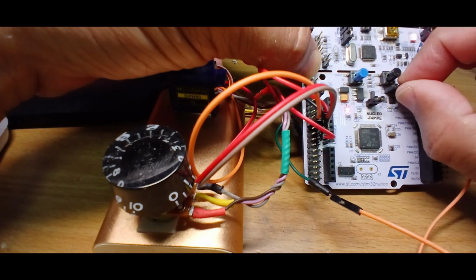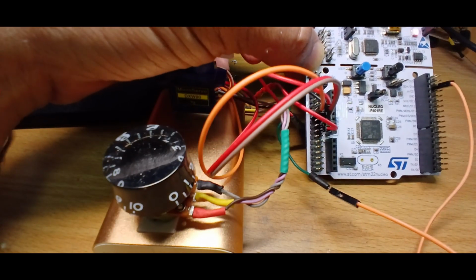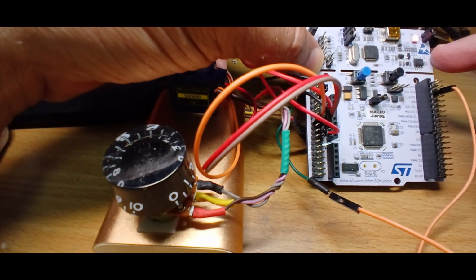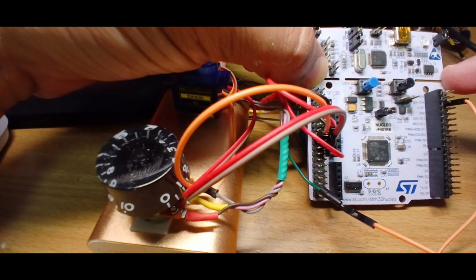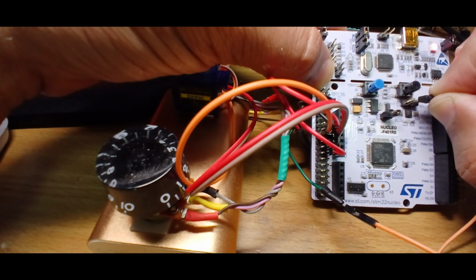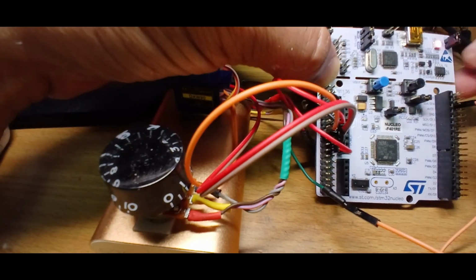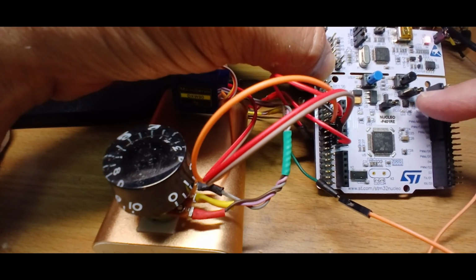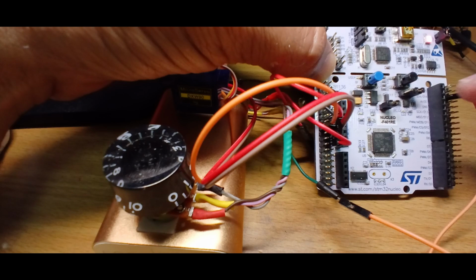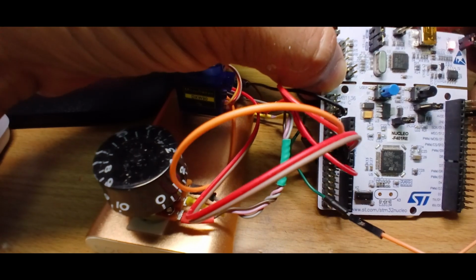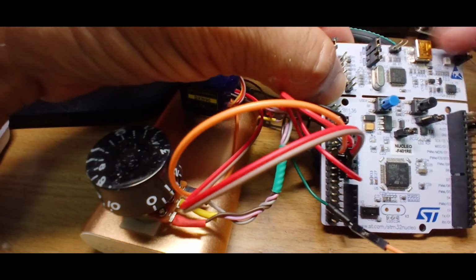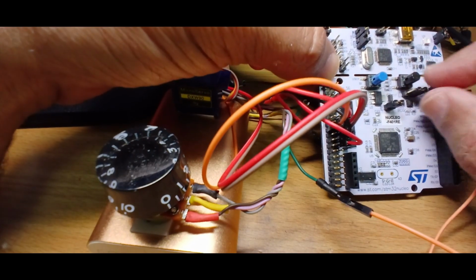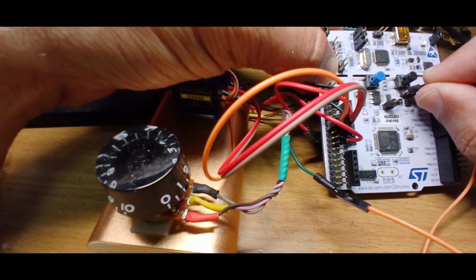But one more thing you need to change. You can see here no light in the board, but the light is here from the ST-Link programmer. If I connect this pin here, what is happening? Still there is no power to the board. It is the original setting. This means if we connect the power from the USB source, then it will come. But now it is connected from the VIN pin, so we need to change the jumper.